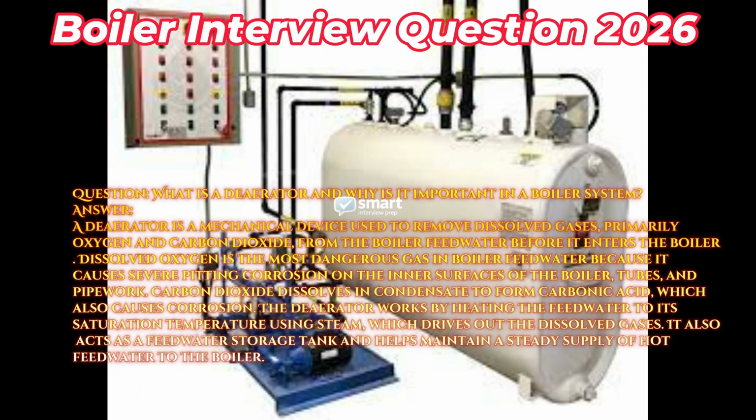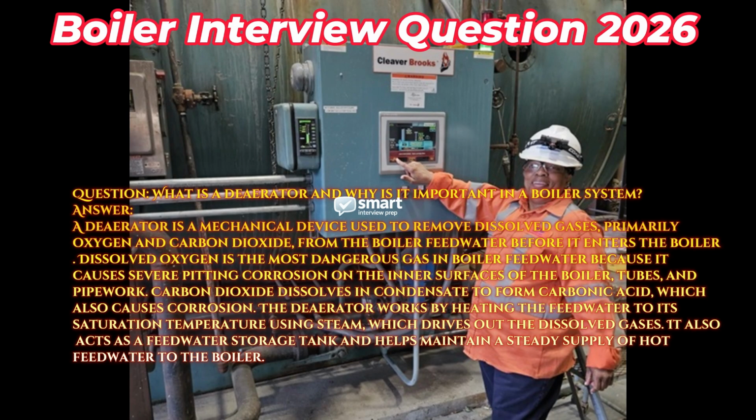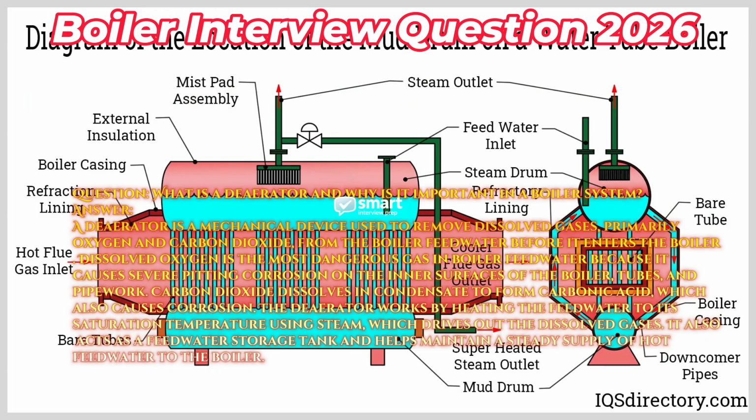Question: what is a deaerator and why is it important in a boiler system? Answer: a deaerator is a mechanical device used to remove dissolved gases, primarily oxygen and carbon dioxide, from the boiler feed water before it enters the boiler. Dissolved oxygen is the most dangerous gas in boiler feed water because it causes severe pitting corrosion on the inner surfaces of the boiler, tubes, and pipework.